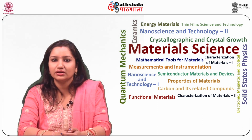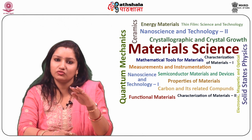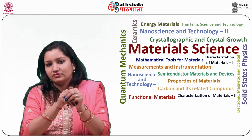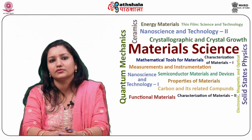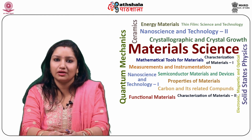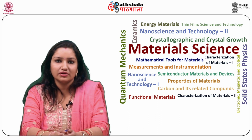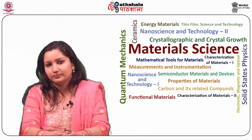With a manufacturing technique called stacking, several layers of amorphous silicon solar cells can be combined, which results in higher efficiency rates, typically around 6 to 8%. Only 1% of the silicon used in crystalline silicon solar cells is required in amorphous silicon solar cells. On the other hand, stacking is expensive.